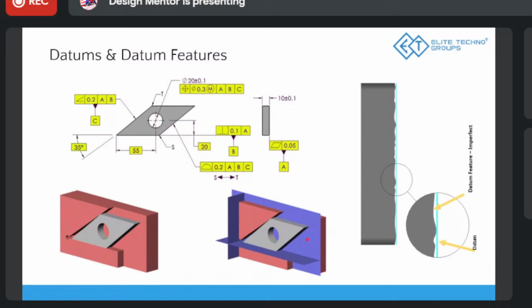So we have placed it like this, and we place it down below, right? You can see here, datum B. This surface is datum B. So we place it down here. Now it is locked like this also, and then we place it by this diagonal surface. See, this diagonal surface is labeled as datum C. Now it is completely locked. Now you can exactly see there is a gap in here, which means somewhere there was an issue with manufacturing. And if you put it into a part, it will look like this.